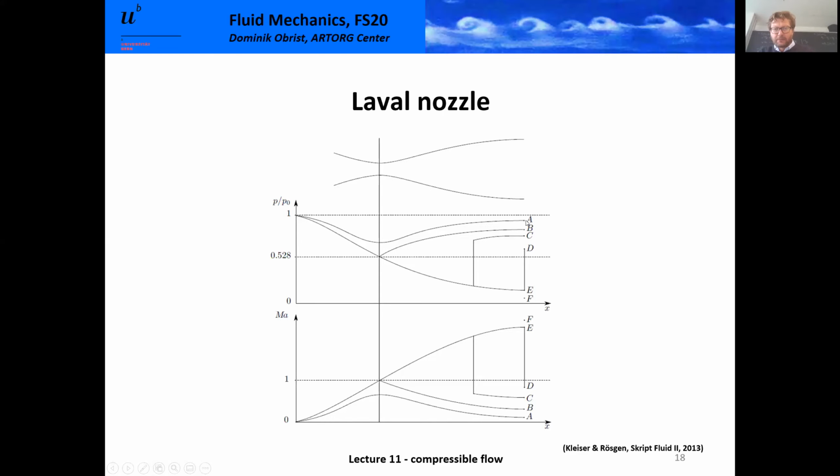As we lower the pressure from PA to PB, we're coming exactly at this critical state where we exactly reach this critical point where Mach 1 is reached. However, because the pressure is too low, we're just returning again at this bifurcation state to the subsonic condition. Only when we change the pressure and reduce it even further from PB to PC, let's see what is happening.